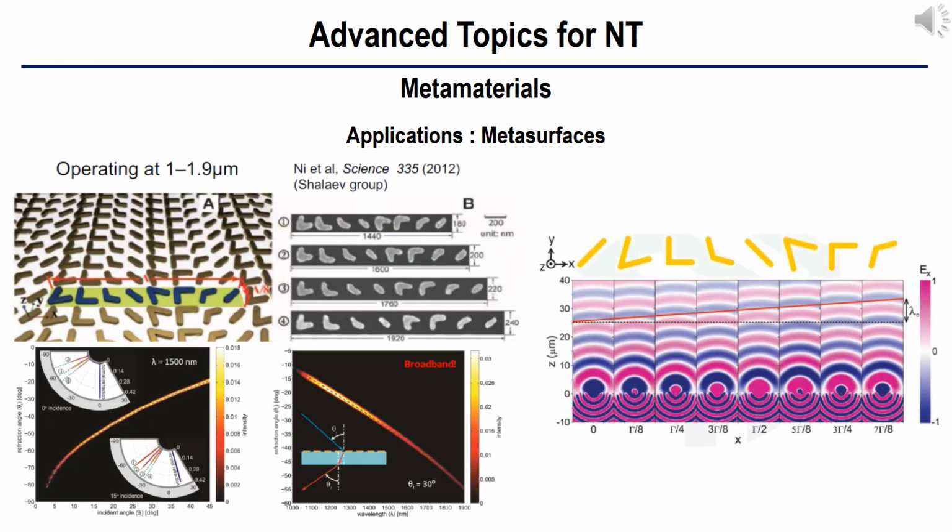There are common ingredients for metasurfaces. First, they should have sub-wavelength thickness. Second, they should be associated with flat composite structures. Third, the sub-wavelength structure should be engineered to control electromagnetic properties. Fourth, they should affect waves through modified boundary conditions instead of effective properties.